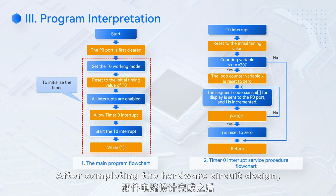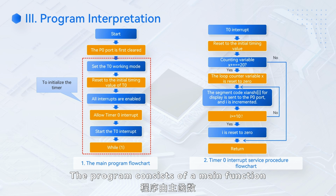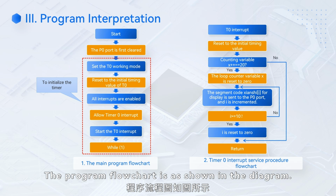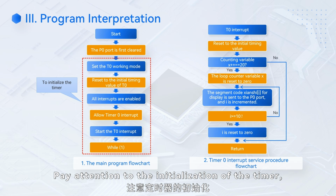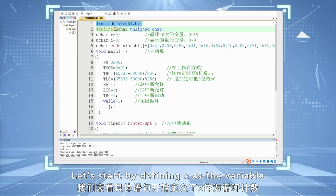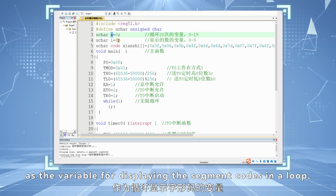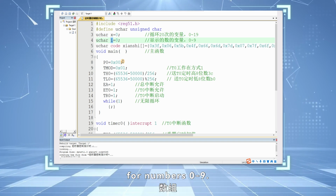After completing the hardware circuit design, the next step is programming. The program consists of a main function and an interrupt function. The program flowchart is as shown in the diagram. Pay attention to the initialization of the timer, which involves determining the function and mode of operation, presetting the initial value, enabling interrupts, and starting the timer. Let's start by defining x as the variable for counting 1-second cycles and i as the variable for displaying the segment codes in a loop, and setting up an array to store the segment codes for numbers 0 to 9.